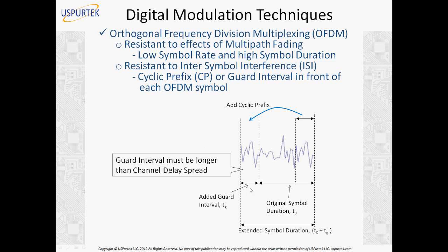So once we have this cyclic prefix in place, what we are doing is copying a part of the information which is already present in the symbol and putting it in front of the symbol. So there is redundancy in the symbol itself. Even if at the head end or the tail end we lose part of the signal because of inter-symbol interference, still we have a copy of it available. This will reduce inter-symbol interference. Now there is a question here, why do we use CP, the cyclic prefix? No, it is not to reduce distortion, it's to reduce the inter-symbol interference.